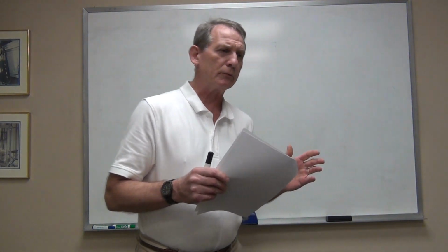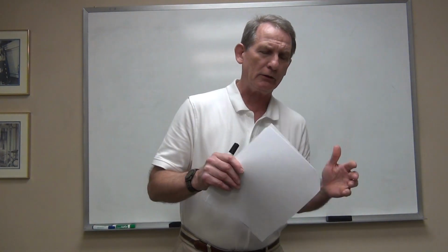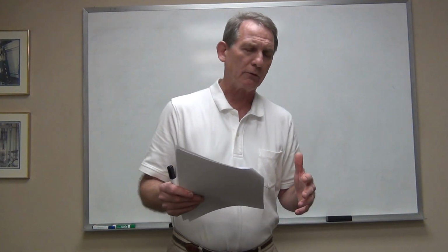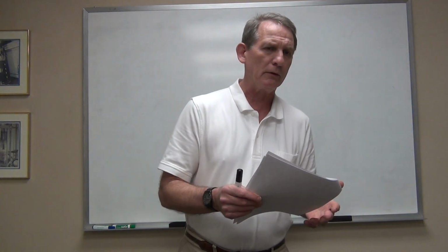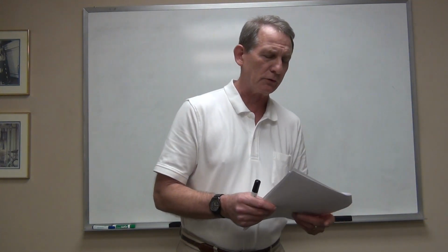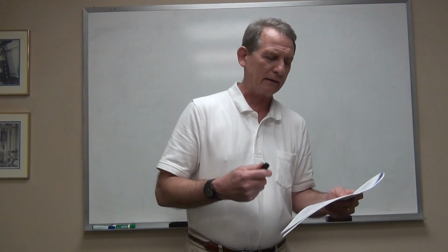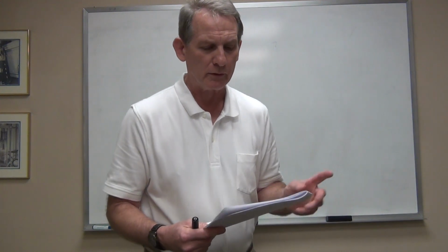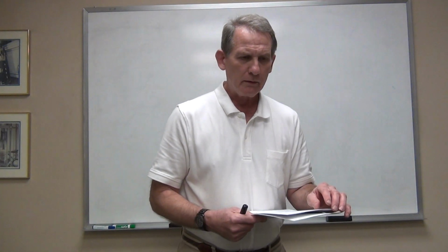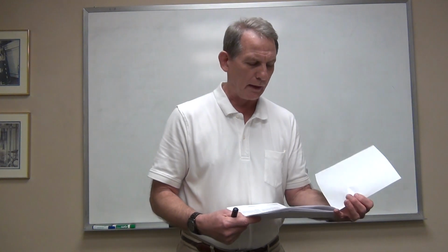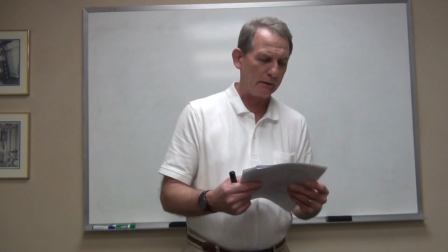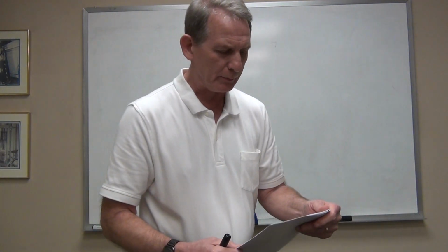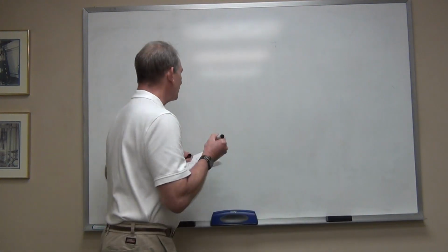Now, over the years, the datum symbol and the way it's been applied has changed a little bit from one standard to the next. So what I'm going to cover is the current way it is done. It was done in a number of different ways over the years, so if you have an old drawing, it may not exactly conform to this, but pretty consistently now on newer drawings, especially on CAD drawings, you're going to see the datum symbol applied as I'm going to explain it here. Okay, so the datum symbol is deceptively simple. It is a rectangular box.